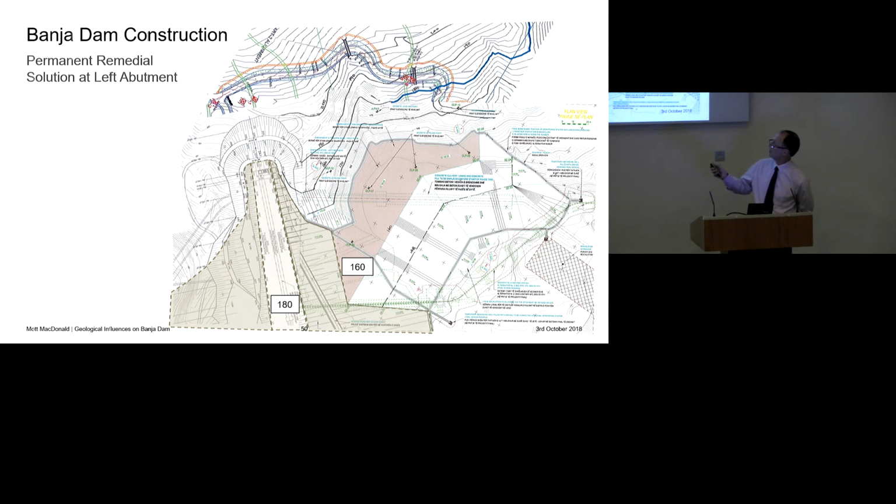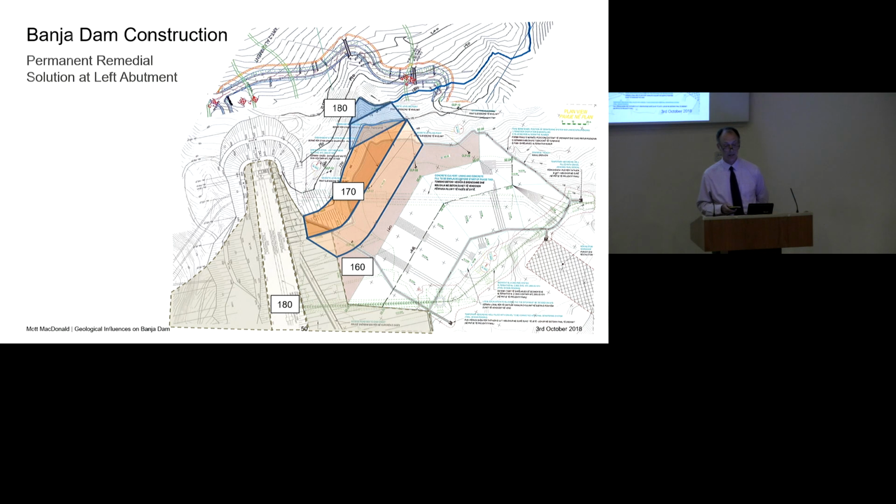And this feature here is the road that serves the village higher up the mountain. So we were worried about that, and through further design review and interfacing with the designer, we said that you should increase the height of the toe berm and wrap it around the nose of the downstream shoulder and protect it in that way, and that would stabilise that and the road. And in fact, it went further than that because there were still further failures or movements that could have led to failures, and in the end we suggested that they should actually raise it even further. So these were sketches that I did as part of the design review process. We were going backwards and forwards discussing and commenting on stability analyses that were being done in order to get to the right solution.